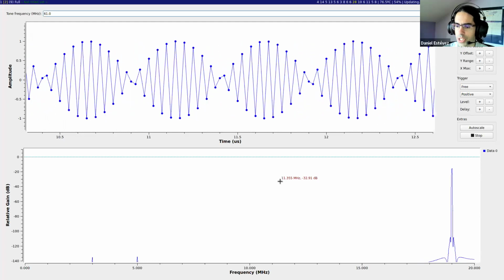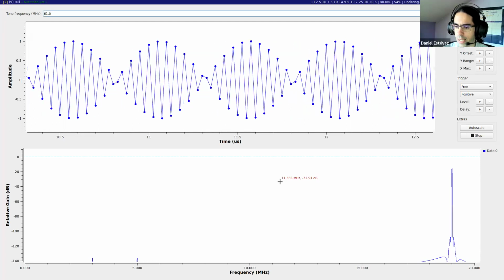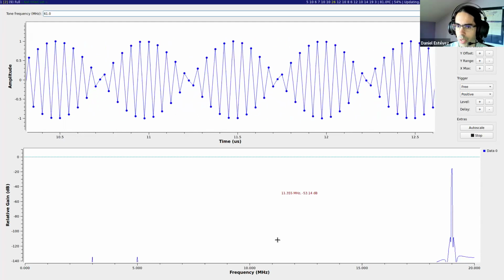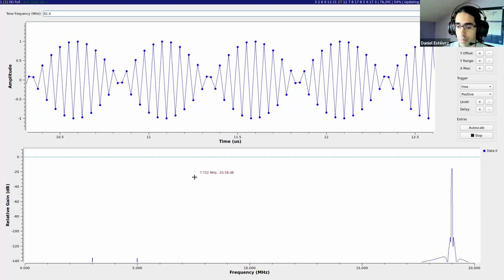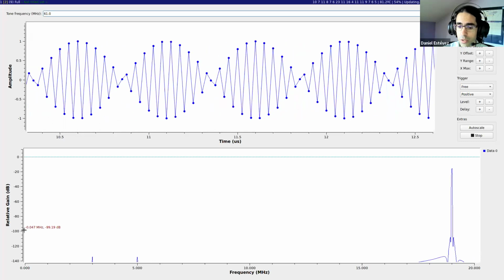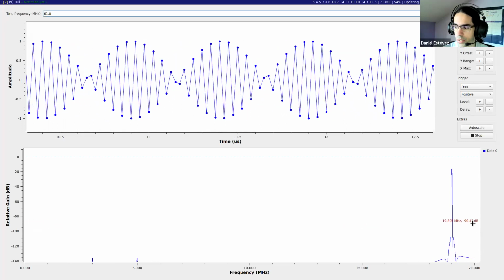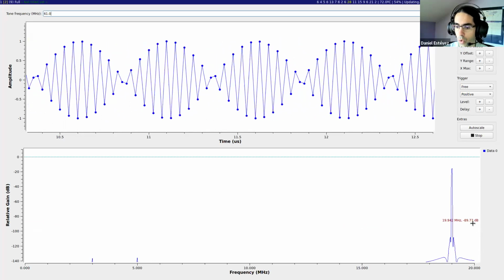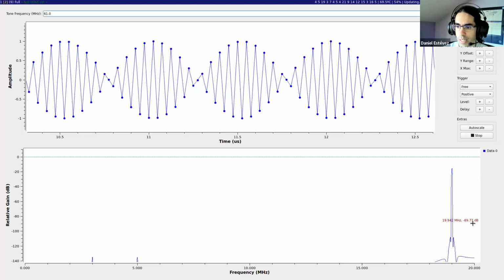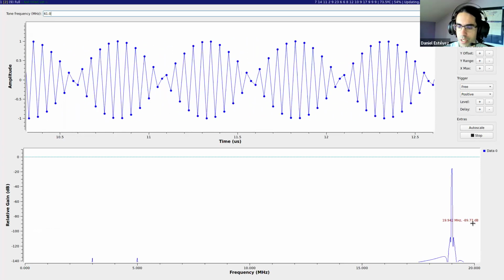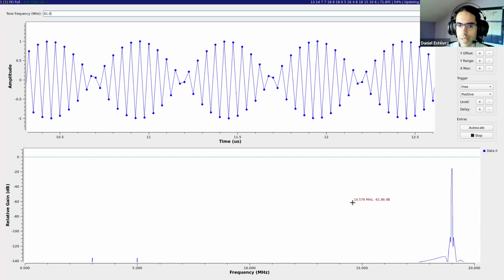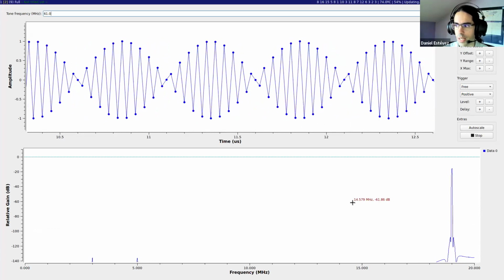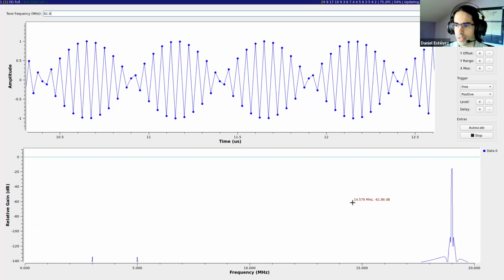So this is how digital sampling works. This is the Nyquist theorem. It tells us that with 40 million samples per second, with 40 megahertz sampler rate, we can only represent from 0 to 20 megahertz worth of spectrum. Or in general, if we sample at a rate f, we can represent from 0 to f divided by 2. Any questions at this point? This is quite fundamental about signal processing.